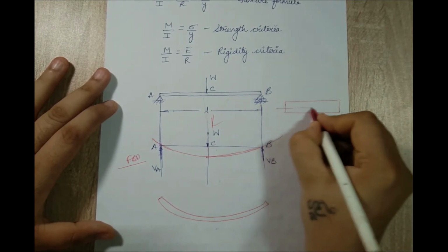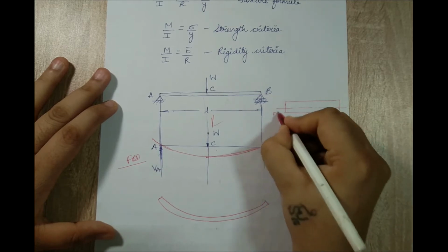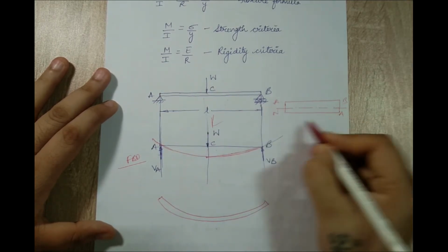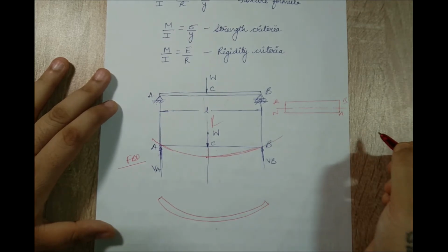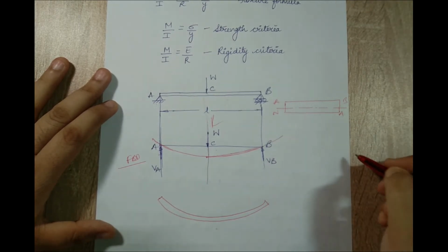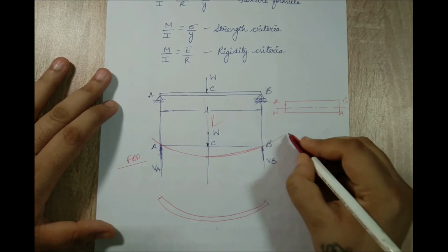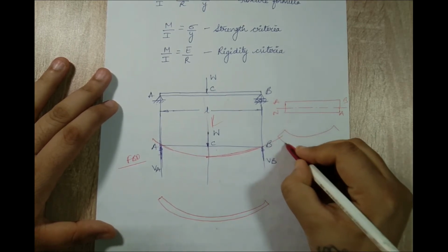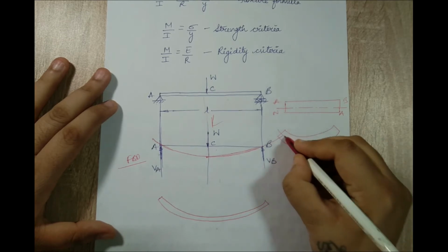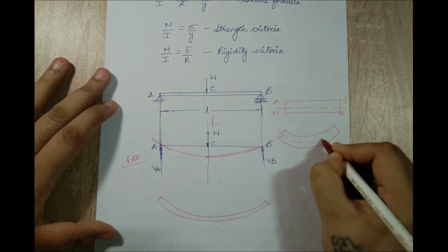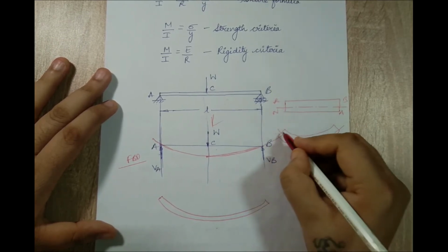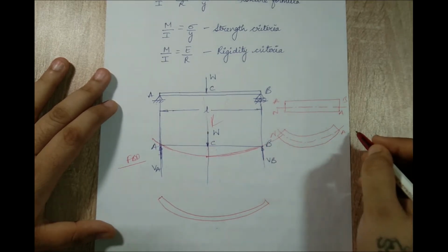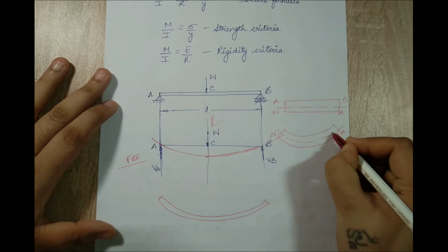There will be an axis which will be called as a neutral axis over here. Okay, this is obviously that beam AB. I have drawn over here which is called as neutral axis. Now, what is this neutral axis? We actually see this axis when you bend the beam. Suppose if you see a sagging kind of effect, this will be that neutral axis which you are seeing over here. Now, neutral axis is nothing but the axis about which you don't see any effect of stresses.